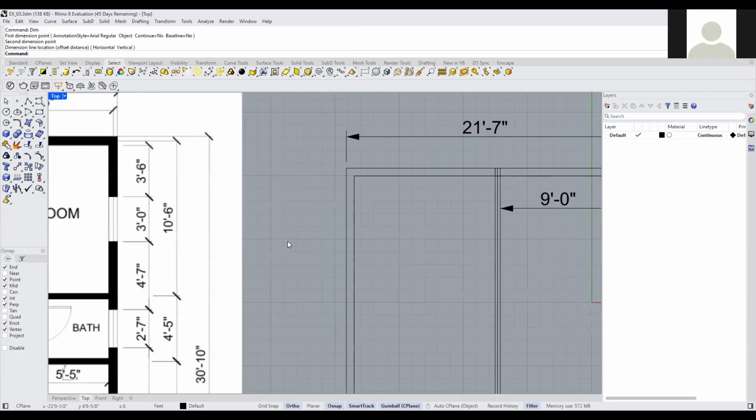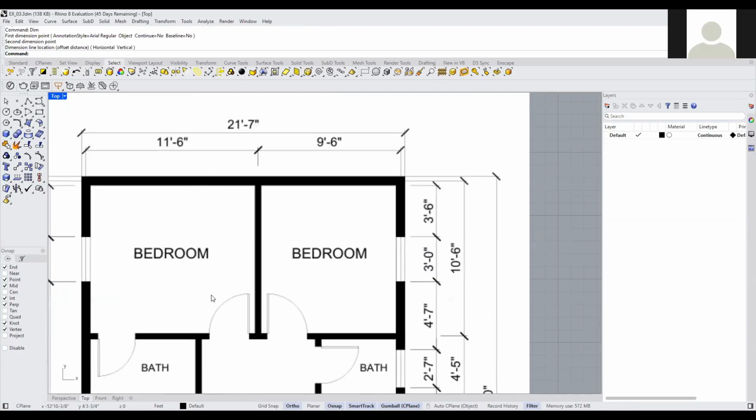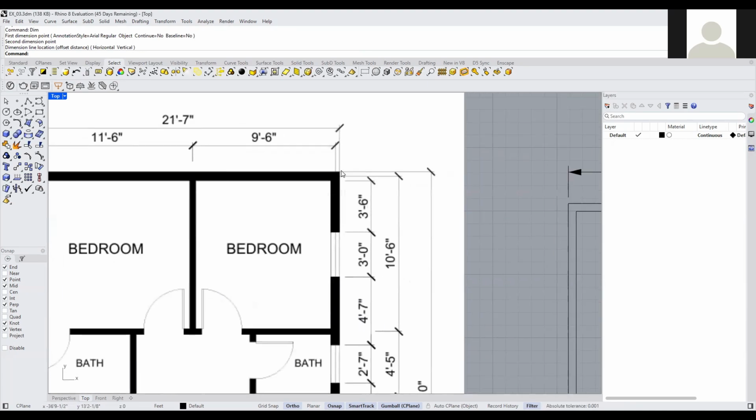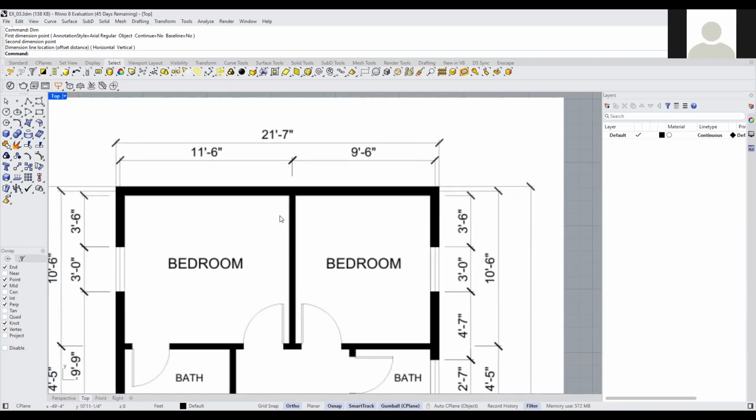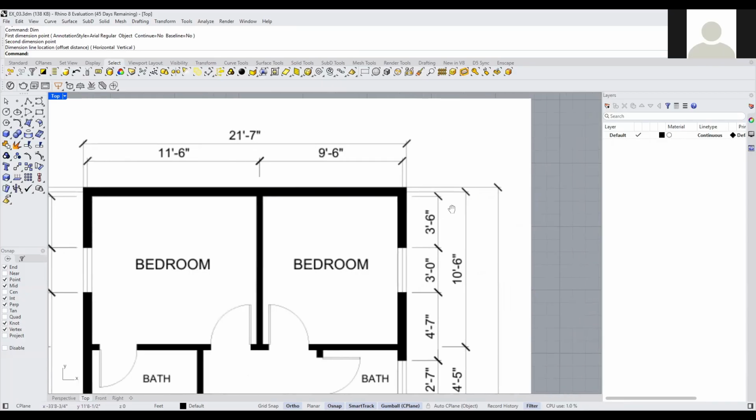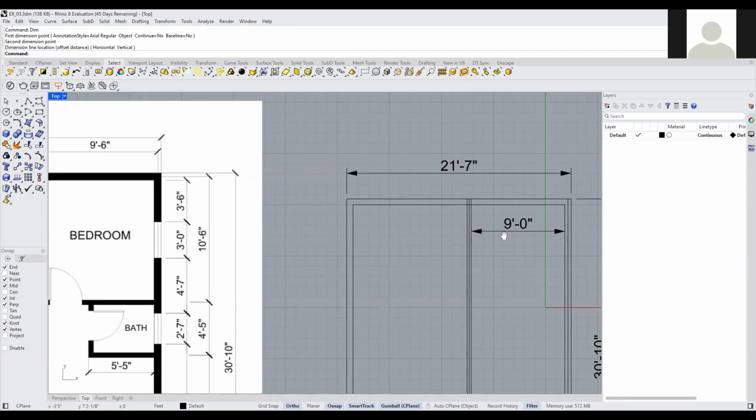So here, because in this plan, in this drawing, we don't have it, I just added center by center of these walls, right? Just remember that we do have this dimension, center to center of this wall, exterior and interior. If you see something like this, you have to draw these lines or walls from this center to this center, and then give it a thickness, as I did.